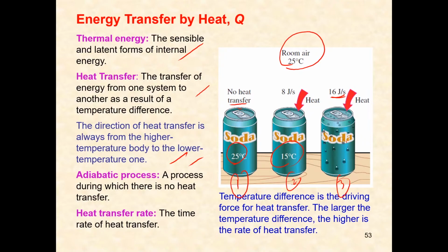If one body is too cold in a very humid place, the humidity in the air will be condensed. The humidity, which is the water vapor, will be condensed on the cold surface. That is why, if you wear eyeglasses and sit in a car with a very cold air conditioning system, and then leave the car in the hot sunny afternoon, you can notice condensation on your eyeglasses. The eyeglasses remain cool at the moment you exit the car, and due to the high humidity in the climate, the vapor in the air becomes liquid on the surface of your lens.